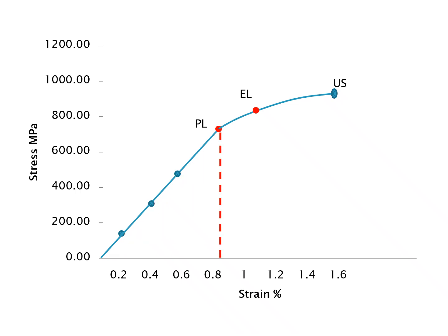Next, the area of the curve till the proportional limit is called the resilience of the material, which means the material's ability to absorb forces and spring back. And the total area under the curve is called the toughness, or how much total energy is required to fracture the material.